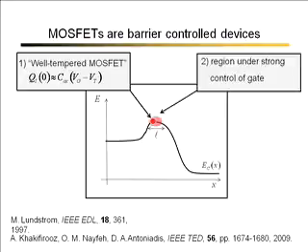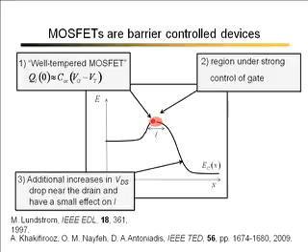So you've got a region near the beginning of the channel that's strongly under the control of the gate and weakly influenced by the drain voltage. If you've designed the transistor well, that's what you hope to achieve. So there's a region there, just with some length, script L, that's some fraction of the entire channel length, that's controlled mostly by the gate, not by the drain. Now, the rest of the channel is controlled by the drain potential. And as you increase the drain voltage, you mostly just influence the potential in that region.